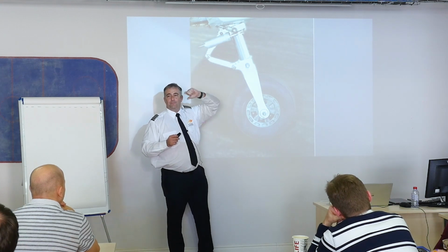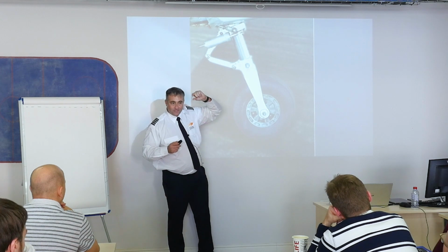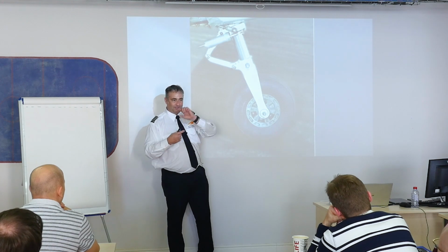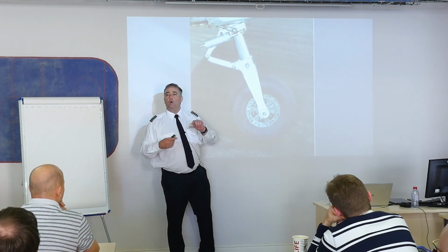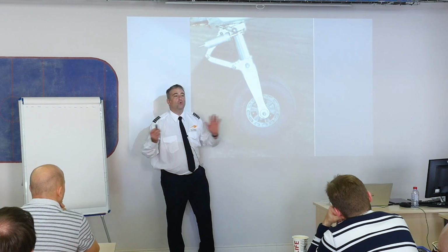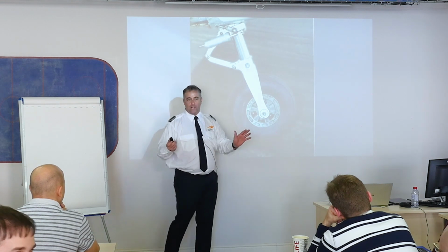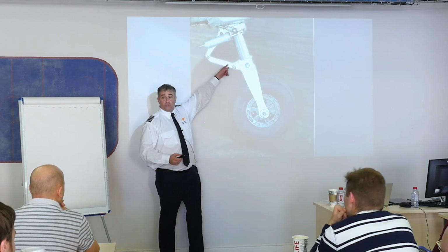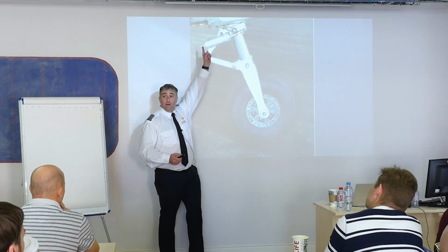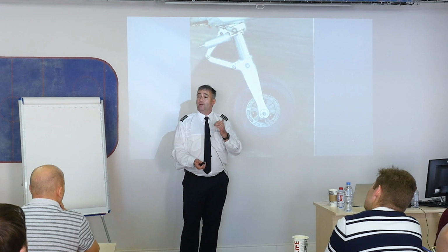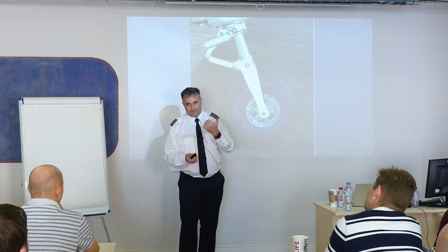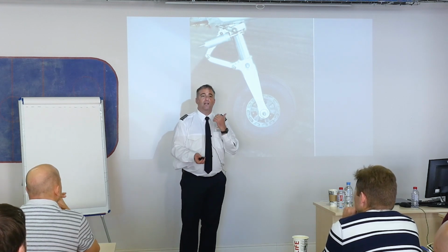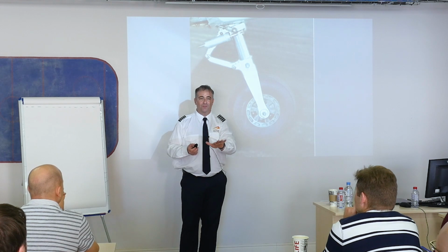Metal. Anybody like Oreo cookies? You guys know what Oreo cookies are? Oreo cookies have the black cookie and then the white center. Okay, Oleo. I don't know who in the world named this. The guy must have been named Oleo. That is an Oleo strut, meaning that this is a strut, and it has a cylinder above it, and that cylinder is charged with some sort of spring or usually gas, nitrogen. It has fluid and nitrogen inside there, and it allows for a nice smooth landing.